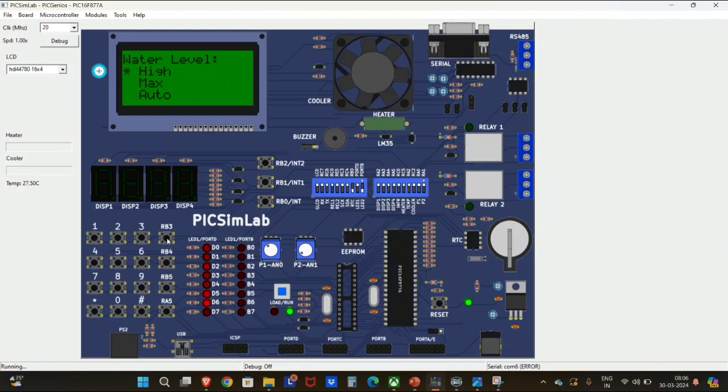So I am long pressing the switch 4, and it will give me a start or stop screen. So as you can see, I can start the program by using the switch 5. In order to stop it, because if I made a mistake while choosing washing program or water level, I can again reselect it by pressing switch 6.